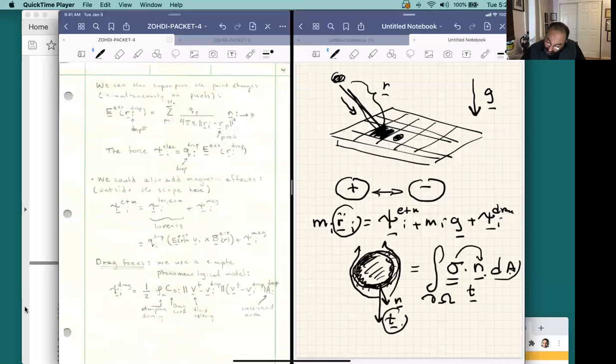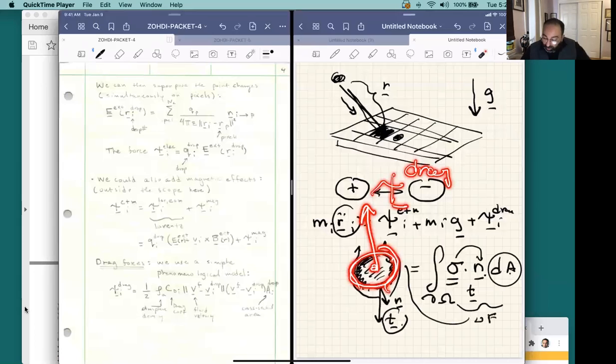You multiply it times the area A, and we get a little force, delta F. We add up all the delta F's all over the surface of the object. And if we integrate them properly, we get a single force, and that single force is called the drag force. That's something that I believe all of us as undergraduates have seen. The problem is, this is not an easy thing to ascertain because there's one big sticking point. How do we get this stress?